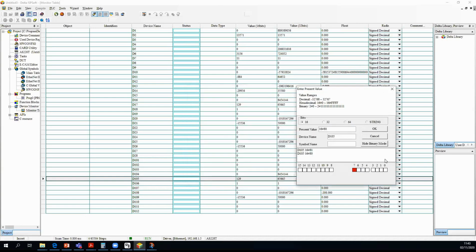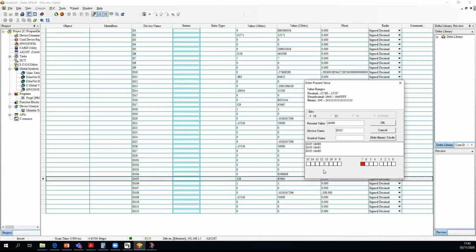So now if I just give the drive a run command, I can actually see the drive moving to its target position. So if I give it another run, you can see it actually moved, this time to position 100,000. So I'm giving it in 50,000 pulses. So that means that the drive is moving in relative movement every time I give it the command to move to a new position.